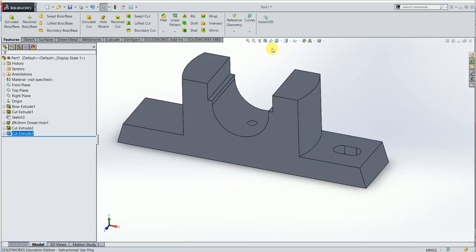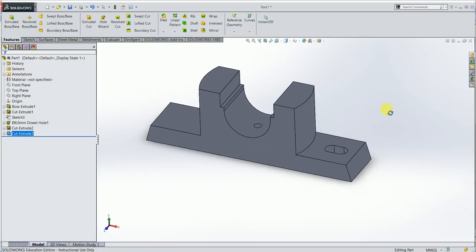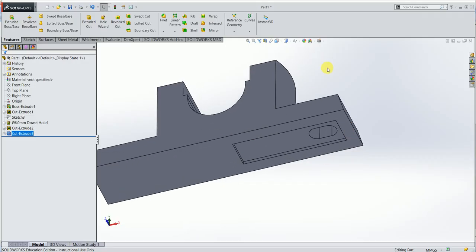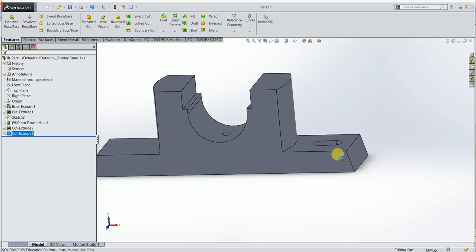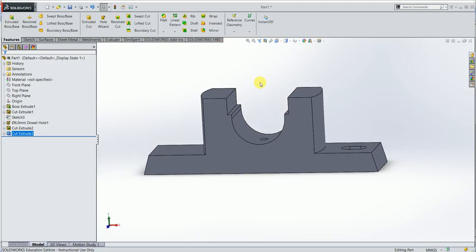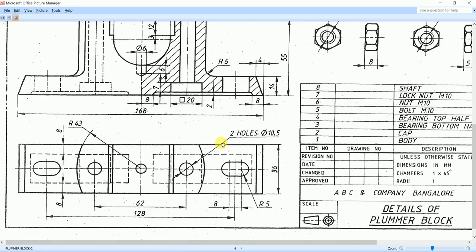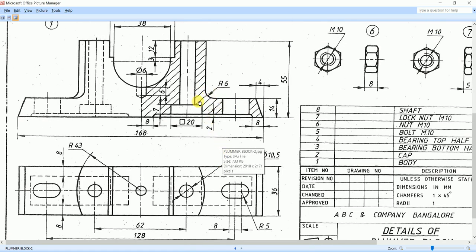So now we can see that if I try to tilt this one, we have made an elliptical wall. So therefore an elliptical wall has been added to the body on the right side from its vertical axis. The same thing has to be done on the left side, but we will do all that by using the mirror option later. So I am trying to add only the features which are present towards the right side of the body from its vertical axis. So this elliptical wall has been added now.